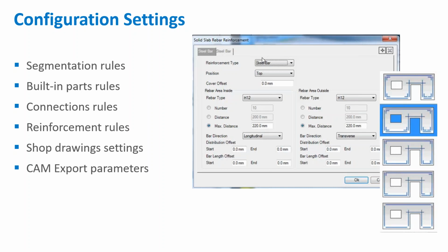One important thing to say is that you can have multiple shop drawings actually for the same assembly. Let's say that you need one for the formwork, so for the guys in the factory to check that the shutters have been placed correctly, and one just with the rebar and the embeds, because these are different fabrication stages basically, so may require different documentation.